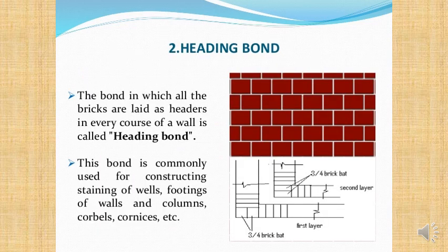The other way we can arrange a wall is by doing something called a header bond or heading bond. And in this example, basically what we're doing is we're taking the bricks, and we're putting the header facing outwards. And so first off, this gives you a thicker wall, doesn't it? So if you wanted a thick wall, potentially you could build it using a heading bond, or alternatively you could do a stretcher bond but just have it 2 blocks thick.